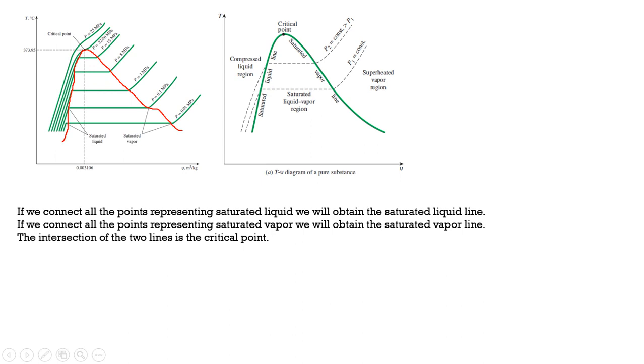At lower pressure, it has the maximum region of the latent heat of vaporization. That is a mixture of liquid and vapor, because the liquid is converting into vapor. At a high pressure, it has the minimum length. You can see this length of the line is minimum. It represents that the latent heat of vaporization is very low. At the critical point, it suddenly changes into vapor.